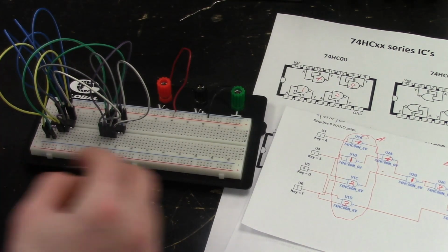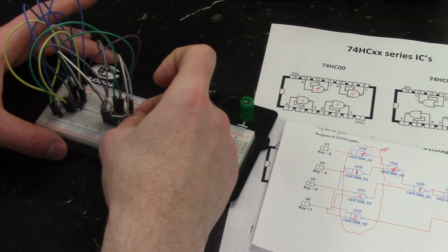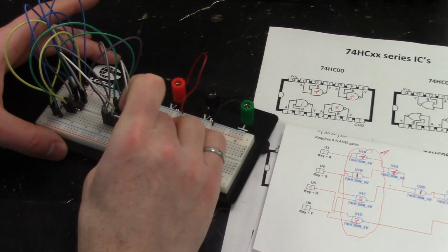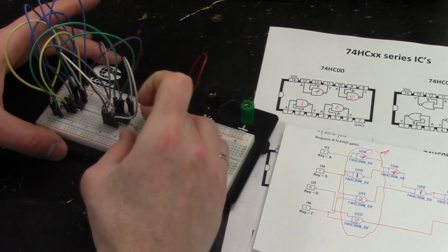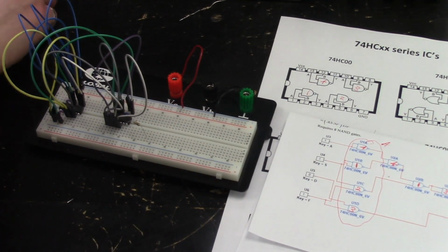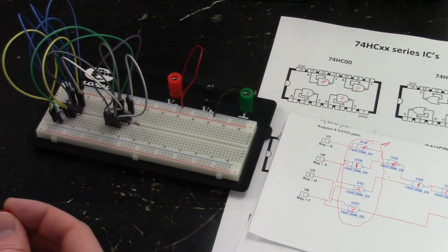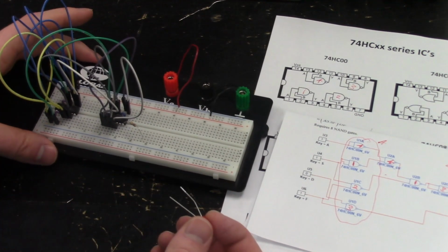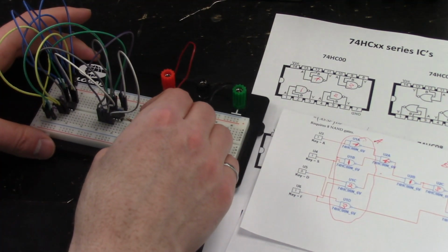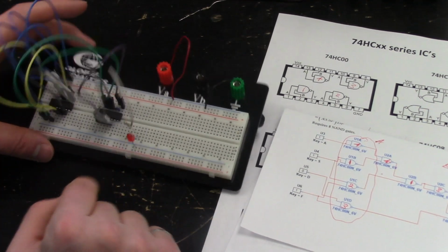So we're going to jump from that with this 1K resistor. You have to use the right resistance. If you don't use a 1K, if you use a smaller resistor, then your LED is going to be really bright because you're running too much current through it. It's going to mess up the logic of the rest of your circuit. And if you use too high of a resistance, then the LED is not going to go on. So we'll go from there into the ground.